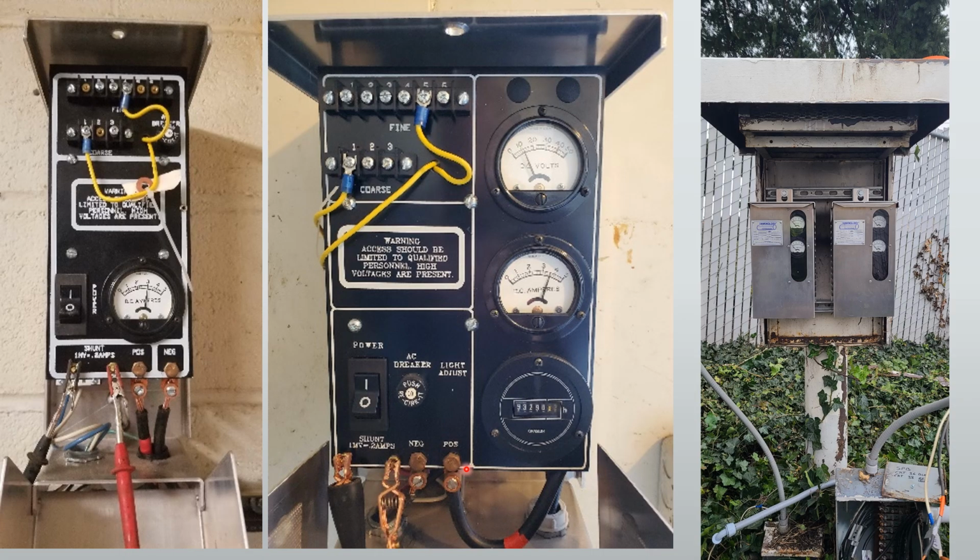Next several slides are just going to give some examples of rectifiers I've seen out in the wild. There's lots of them, so they all come in different shapes and sizes. We have the ES1, does not have a volt gauge, only has an amp gauge. Little shunt, have our positive negative terminal, coarse and fine taps, AC breaker. Nice little system. It's compact. Only goes up to 40 volts, 5 amps for most systems.